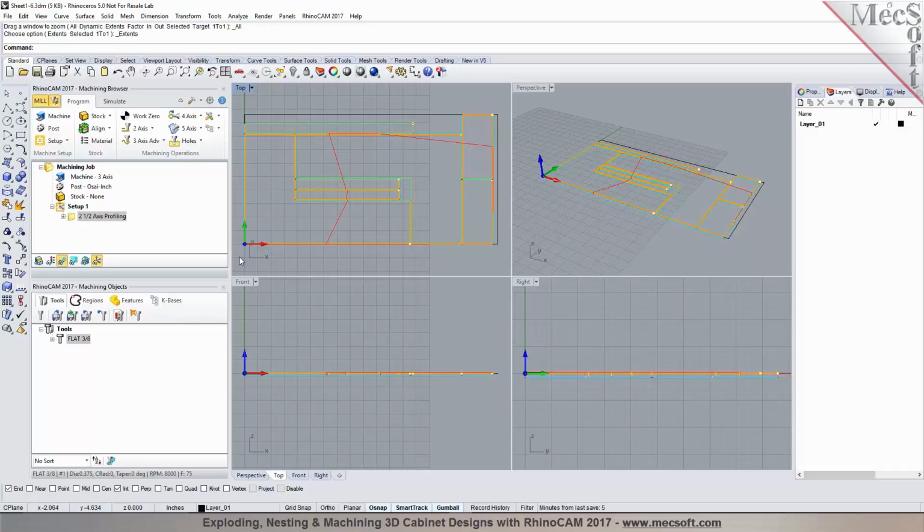Right. Absolutely. Right now I do all this, and then I'm trying to convince the company to pay for the RhinoCam, because currently we have AlphaCam because it works really well with Cabinet Vision, and that's what we generally make most of, just traditional cabinets. It works really well for that. But any parts like this, I always have to draw in Rhino, which I usually just draw in block form just to get a picture to the client. Then I have to turn it into parts, and then I have to turn it into curves, and then I have to export it to AlphaCam, and then I have to nest it.